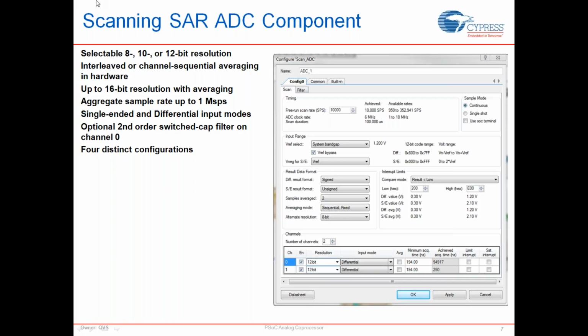There's a sampling part of the component that gives you an option to either set up the ADC to be a continuous sampling ADC, which means once you start your ADC, it's going to keep going through sampling each of the channels and keep providing the results onto the result register. You don't have any control over when to start or stop this ADC. You can't start your ADC and then stop it at a point using an API, but you don't get to stop in between channels, or you don't get to control the sampling itself,